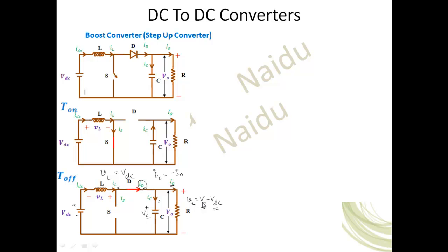Okay, so we assume that load voltage is constant and this is constant. Again the voltage across the inductor is constant, that's why the inductor current will be linear, that means it is a ramp. But now this is getting discharged, that's why it will be changing from max value to minimum value linearly. And capacitor current is actually different now. The ripple current, whichever is there from the inductor current, is flowing through this, and the load current is constant, coming from the inductor current of this one.